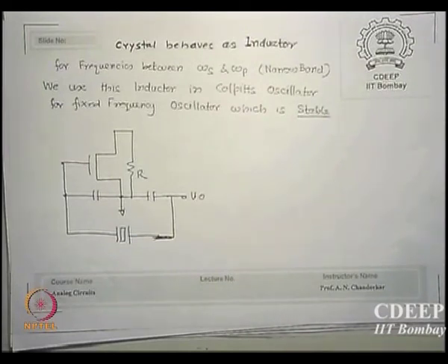Crystal oscillators do not really give their own oscillation per se directly. They fit into a Colpitts combination and you replace your inductance by a crystal.